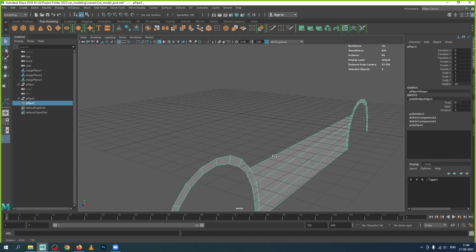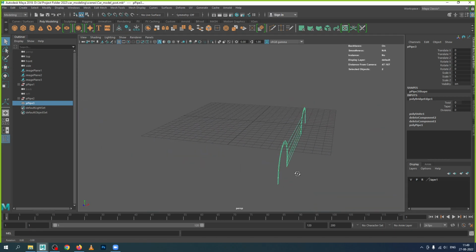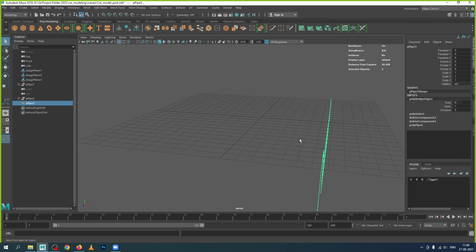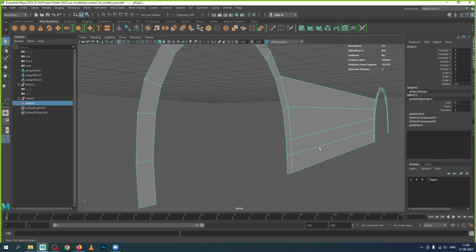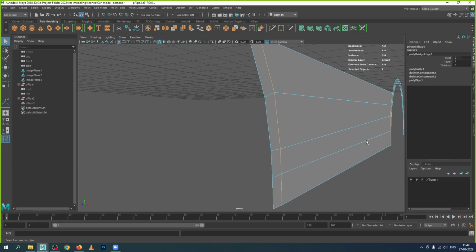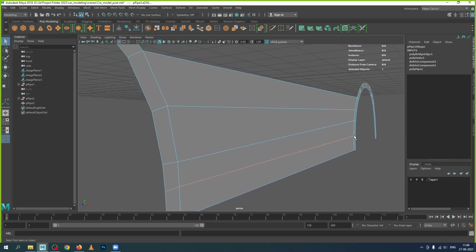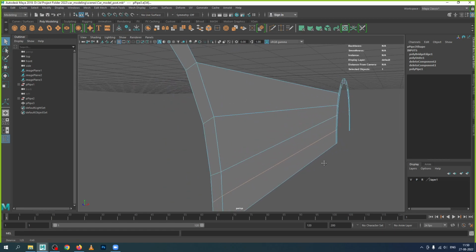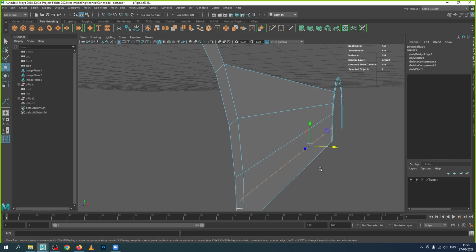Now rotate and see what happened. We got this surface now. Plain surface, flat is there. Slightly I want to modify, I want to give a little depth in this now. What to do? Zoom. Okay, now this area. Now go to the edge. Select this edge, and this edge over here now. 3 edges on this one. What I am doing? I am giving a little depth in this one. Depth in the sense I want to move this one little inside on this.